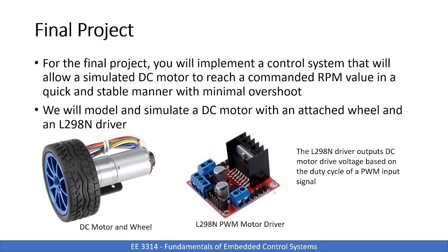If you're interested in getting more information on controlling these, I can give you some more information, but essentially this driver accepts a PWM signal, and it creates a drive voltage for this motor that will make this thing spin at an RPM that is roughly proportional to that drive voltage. It also has an encoder here on the back, this little black piece sticking out.